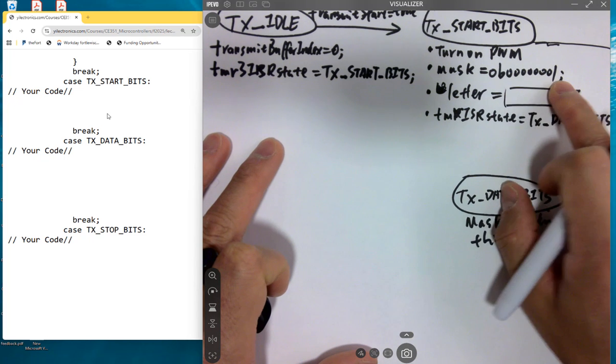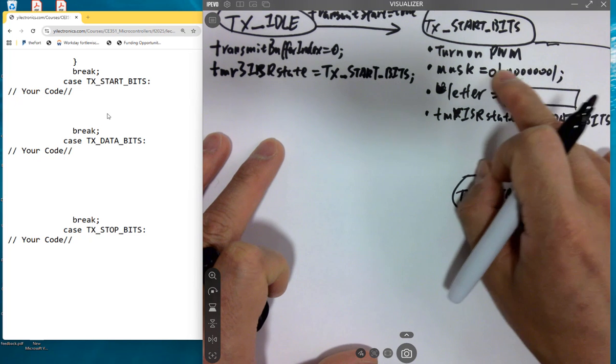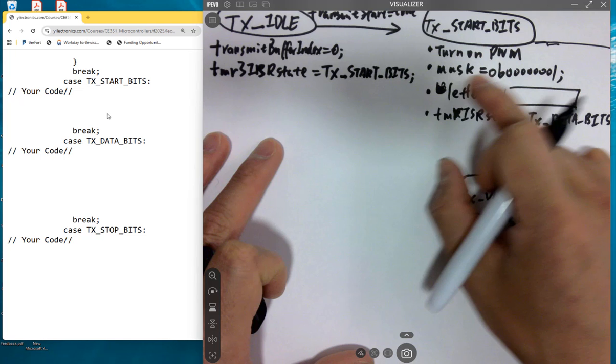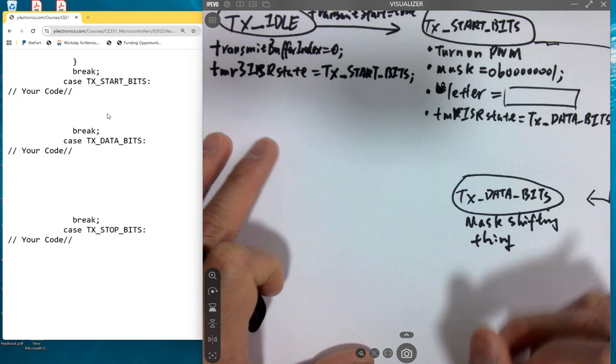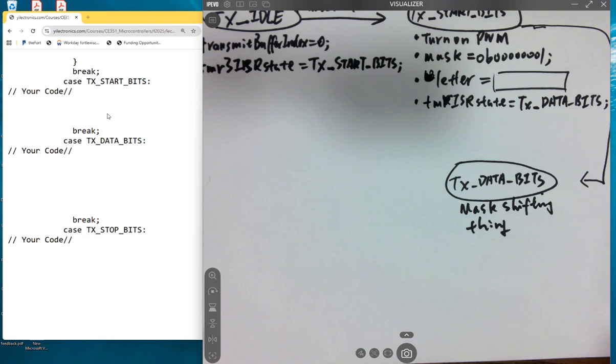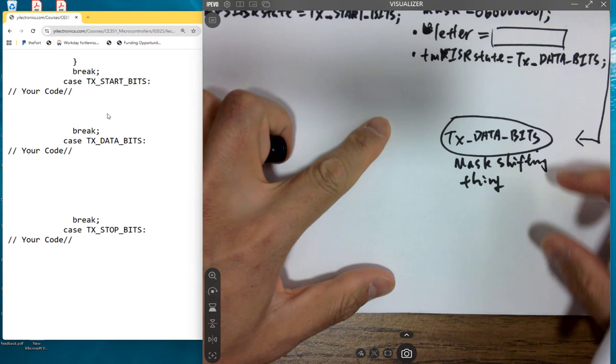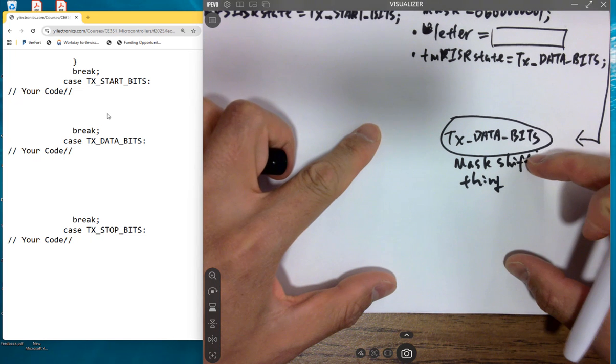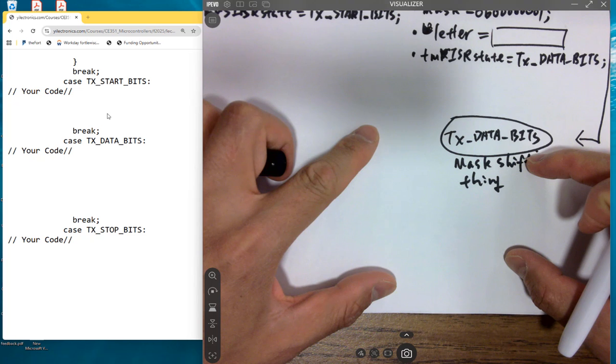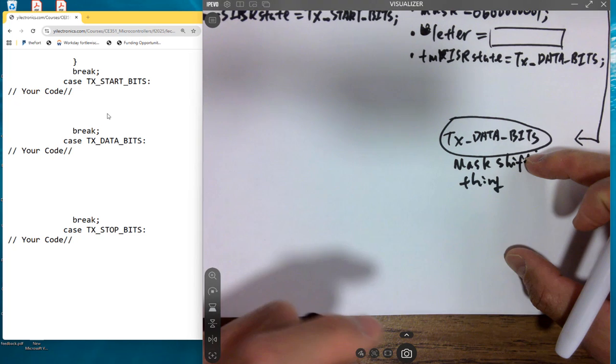So every time it detects the LSB and the second one until the MSB, and then the next time it's shifted out, mask becomes 0, which means all the data, all the bits, are sent. Okay? So how many bits are sent during this state? 8. Okay? 8.